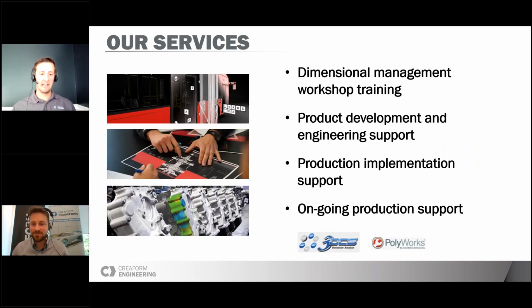Yeah, no, I think you need to start considering this quite early in the design stage. Sometimes even before doing any CAD, you can sketch some concept. What are the parts? What are the manufacturing processes? What kind of requirements? And already start to evaluate: am I going to have good requirements or acceptable variation?